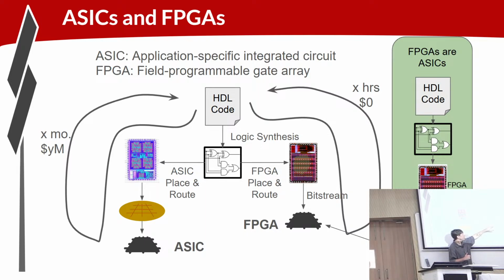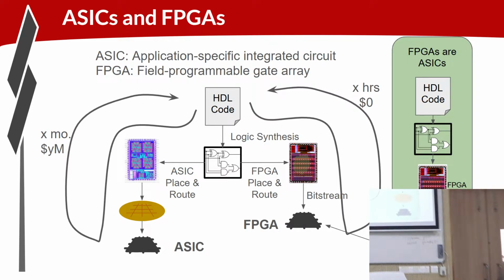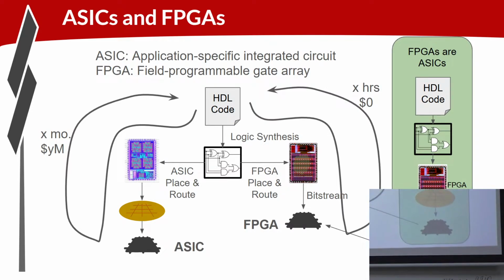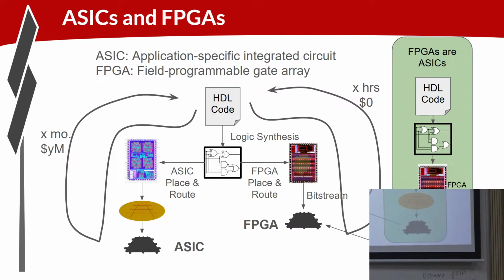Or in the FPGA, you're producing configurations, and that's known as a bit stream, which specifies all the bits that control the individual logic functions, as well as the connections of all the routing to connect up those logic functions. So, the hardware is laid out in a fixed way. You're controlling the settings of these bits that generate that bit stream, and download it onto the FPGA to configure the FPGA for your particular logic function.